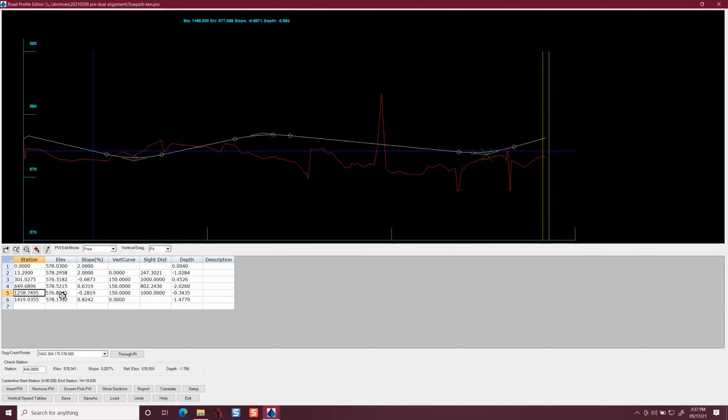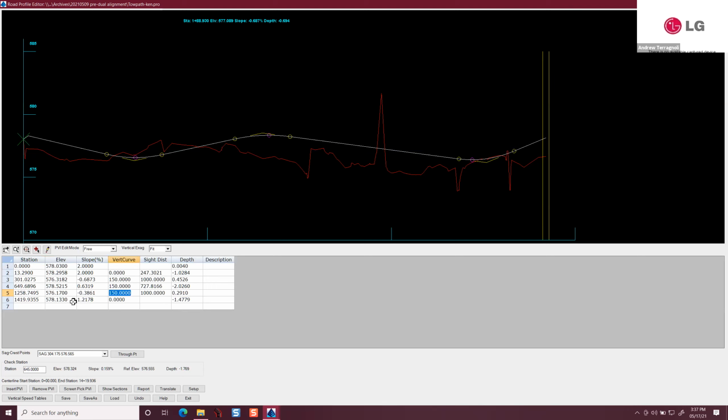It's not going to help you much. What is that? 576.17, yeah. Let's see what it gives you. See, it got it almost up to 0.4. For me, it's not the end of the world, but they're going to say you're going to have to put a lot more catch basins all on slope rather than on sag. So that means this point here is going to need to be just a skosh higher.